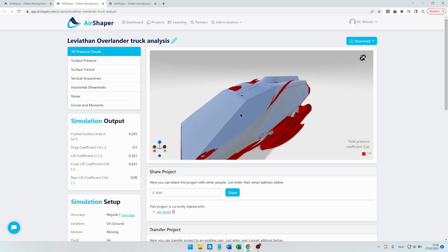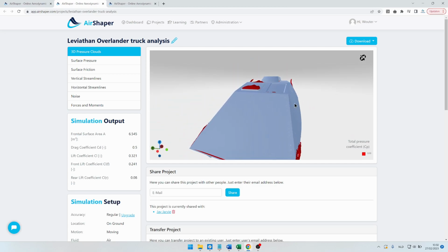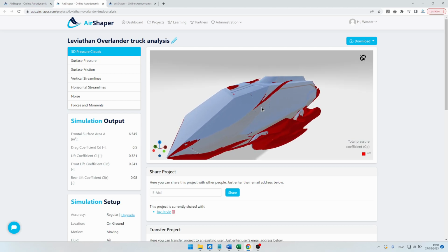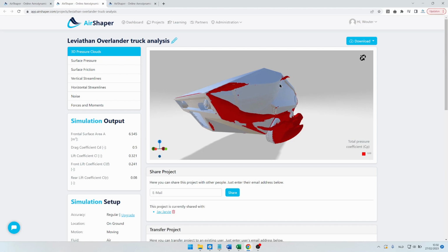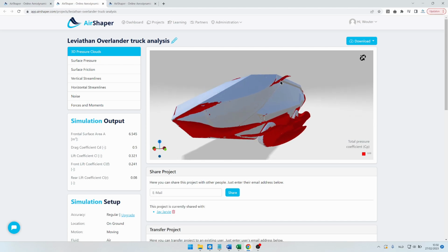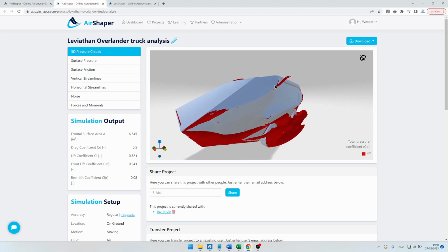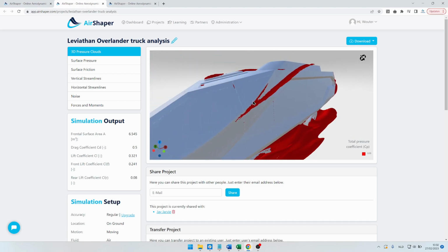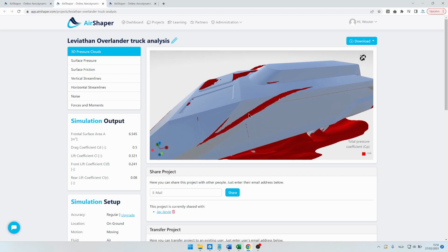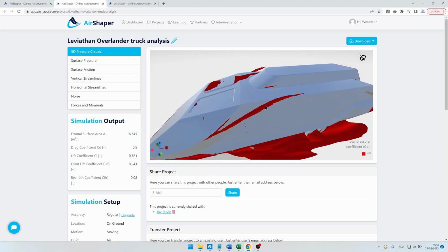So the air stays attached, is being pushed out to the sides of this cabin, and then plunges inward again as it reaches the underside of this cut. So this is a negative movement, an inward movement, and the curvature is too strong, so again the air starts swirling and leaves this vortex behind, which travels upward via the side of the truck.